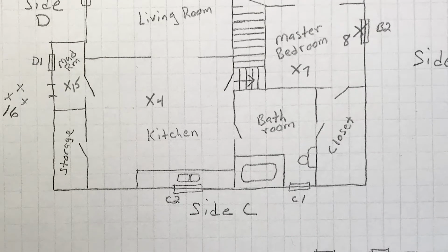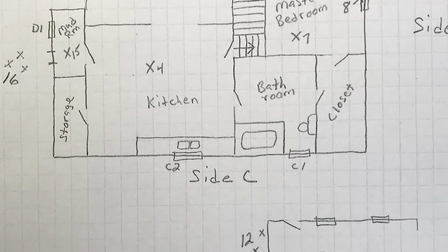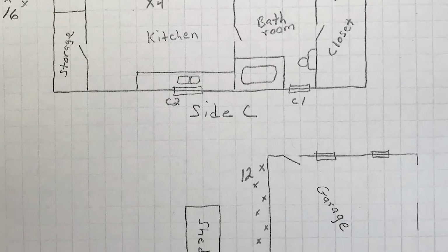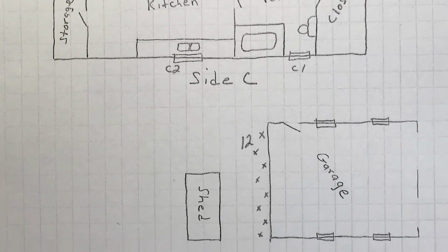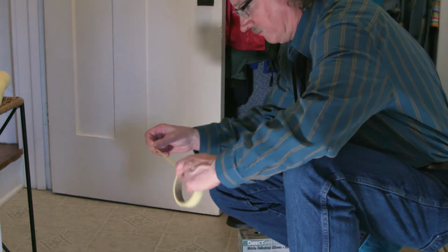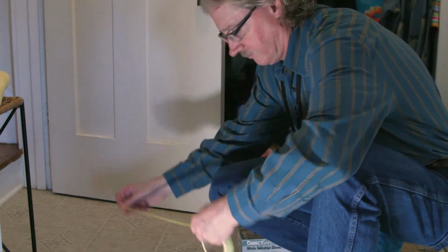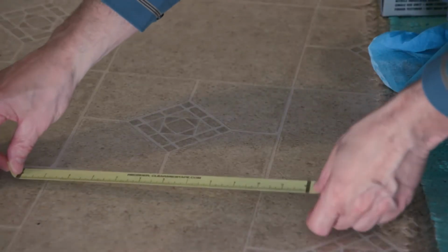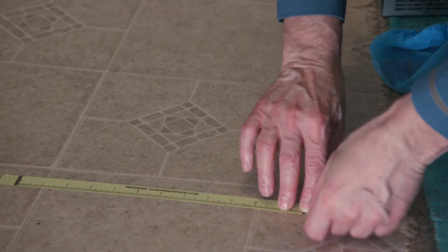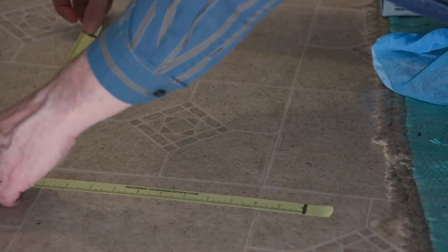The drawing must include the entire yard if a fence, detached garage, or other types of outbuildings were tested, and must show the location of soil samples if any are collected. Once the exterior and interior visual assessment is completed and you have a floor plan drawing, proceed next with collecting dust wipe samples. It is especially important to collect dust wipe samples before any paint chip samples are collected to avoid creating a lead hazard that may not have existed prior to you removing a paint chip.